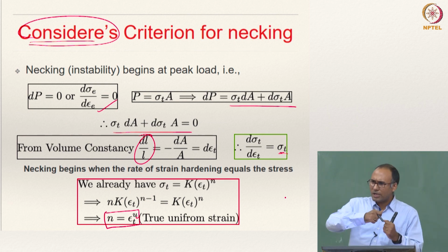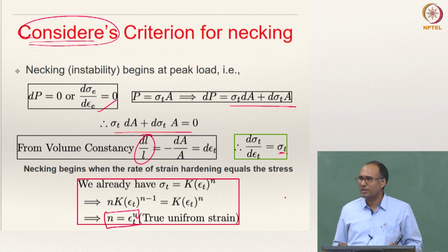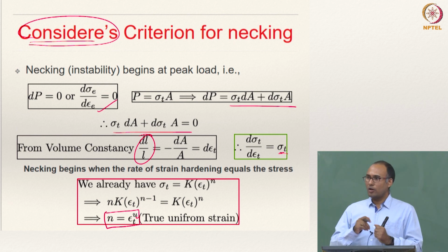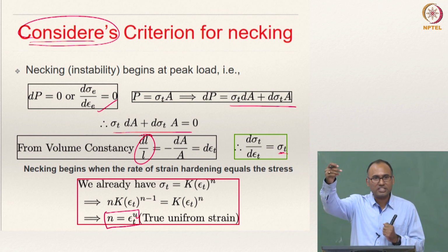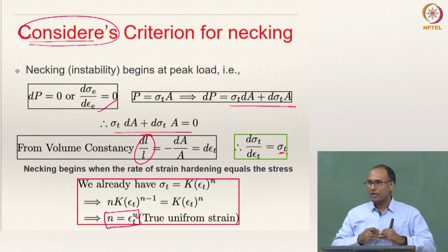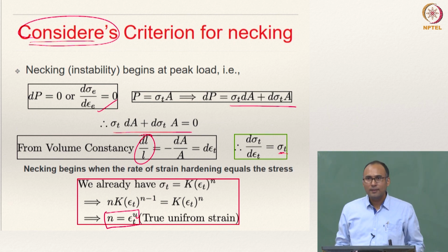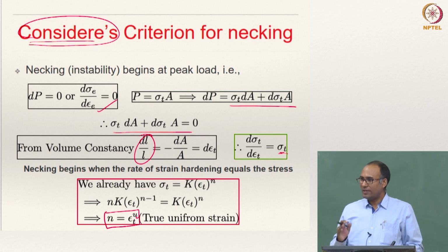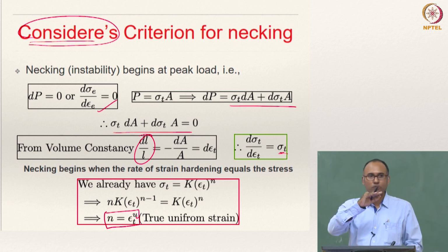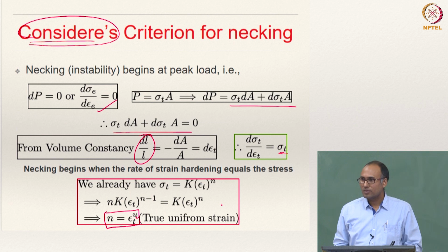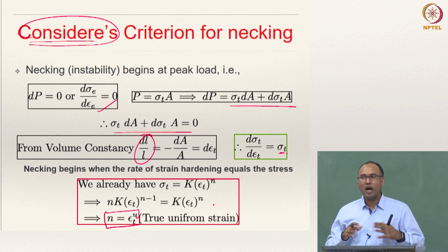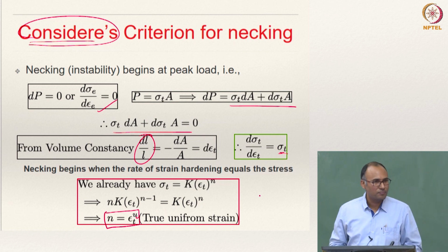That is why we say by doing plastic deformation, you are hardening the material, right? So if you are given a material which is loaded to the plastic regime and unloaded, and you are trying to find out the yield strength of that specimen, you will find it to be more than what it would have been for a virgin material. So by plastic deformation, you can harden or strengthen the material.